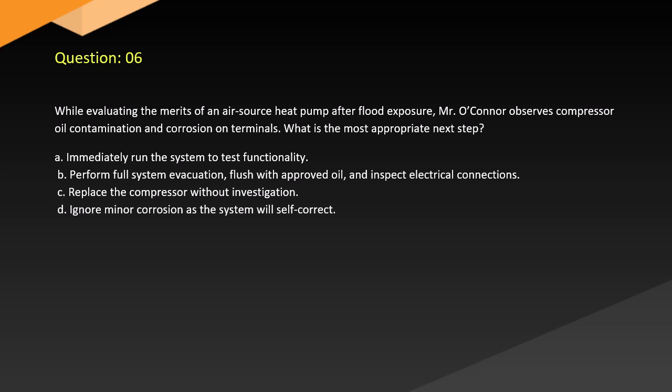A. Immediately run the system to test functionality. B. Perform full system evacuation, flush with approved oil, and inspect electrical connections. C. Replace the compressor without investigation. D. Ignore minor corrosion, as the system will self-correct.